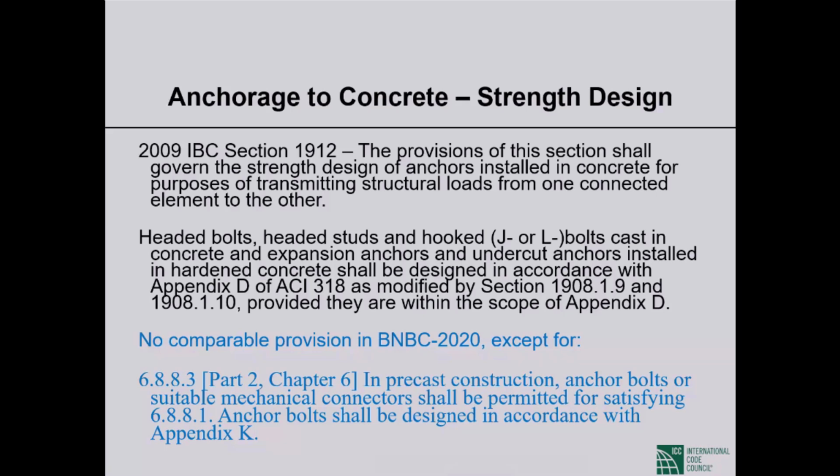Now, you don't have any of that. No comparable provision in BNBC 2020. There is nothing in the code itself that directs you to Appendix K for anchor design, except for something that Dr. Akib found for me, section 6.8.8.3. So Appendix K itself is in Part 2, Chapter 6 of BNBC.